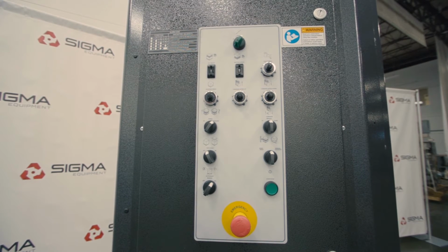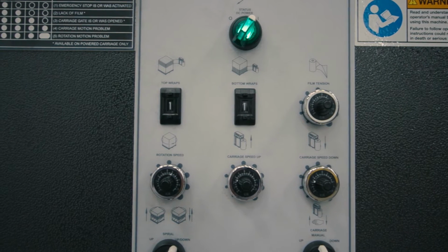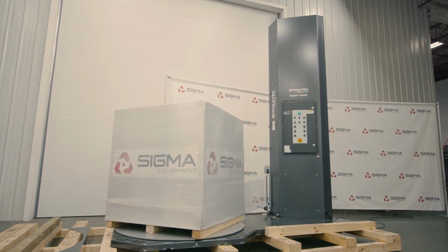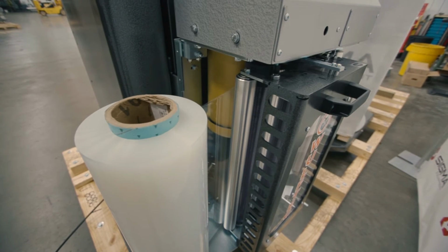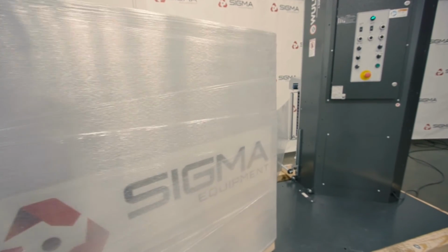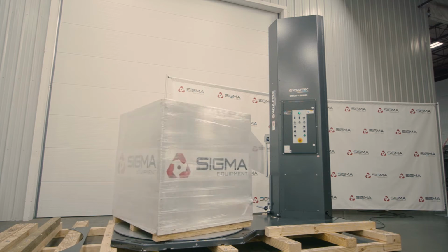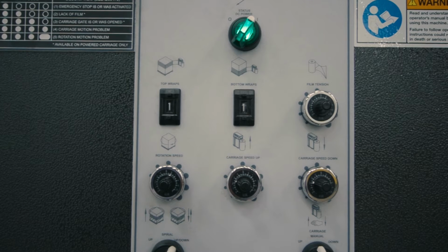The control panel offers many adjustments for the machine. The top and bottom wrap counter allows a user to decide how many full wraps the machine will complete on the bottom and top of the product. The film tension dial adjusts the amount of tension that stretch rollers put on the film before the wrapping application. The amount of tension will decide how much the film will shrink once on the product. The rotation speed adjustment determines how fast the product platform will rotate. There are also dials to adjust the up and down speed of the film carriage.